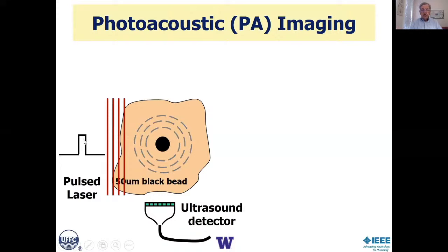Because this light is time modulated, that creates displacements, time derivatives of that, which are particle velocities, which through the acoustic wave equation gives us pressures, which can propagate out. And those pressures can be detected on a traditional ultrasound array. Again, if you put this in the nanoseconds to tens of nanosecond ranges for the lasers, you'll have in the megahertz to tens of megahertz worth of ultrasound frequencies coming out, which is right in the traditional medical range.